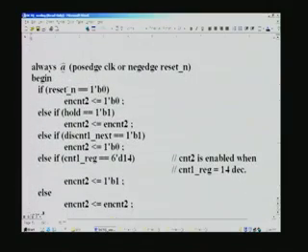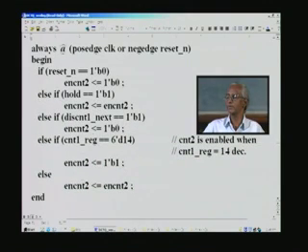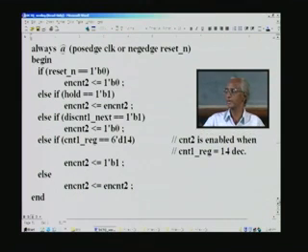So, once again you see in the design one signal in only one always block. This is a good practice, I hope you will follow the same, and if you take hundreds of signals in one always block you will get drowned. So, it is a good practice to have just one signal, and very rarely violating that if the need arises, which we may see later on. And similarly for reset, hold, etc. same, and it has to be cleared if counter 1 is to be disabled.